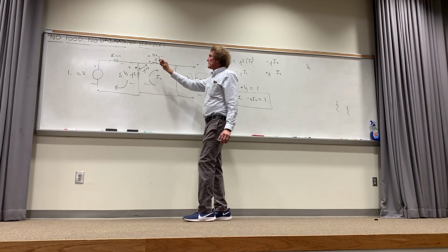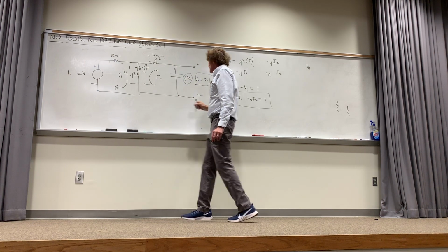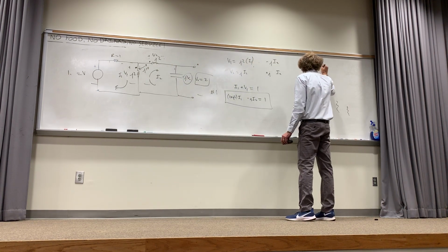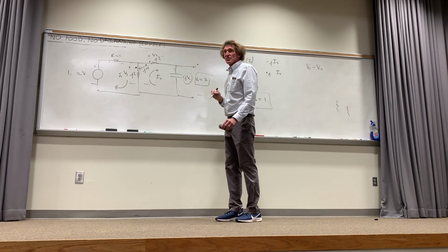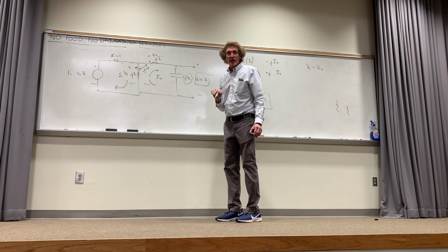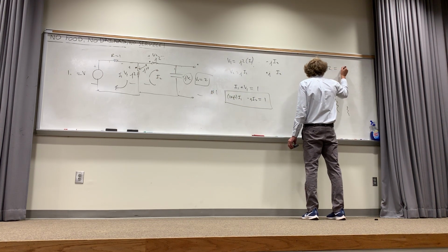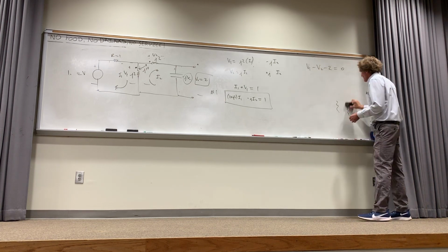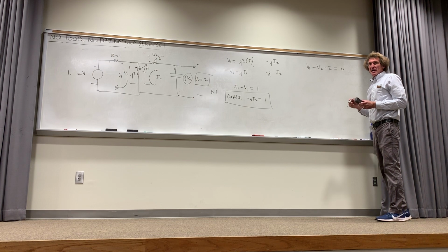And then it's a voltage decrease of V2. Can everybody see that? A decrease, minus V2. And then it's a voltage decrease of 2. Do you all see that? Everybody? Okay. So it's minus 2 equals 0. And again, the only thing I'm doing is making sure I carefully go around the loop, not in a haphazard way this time.